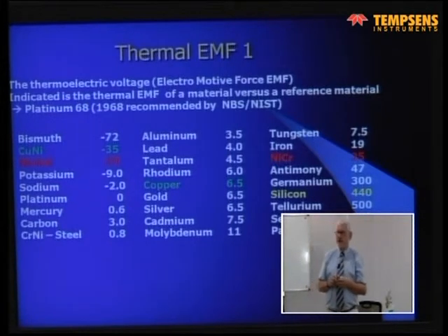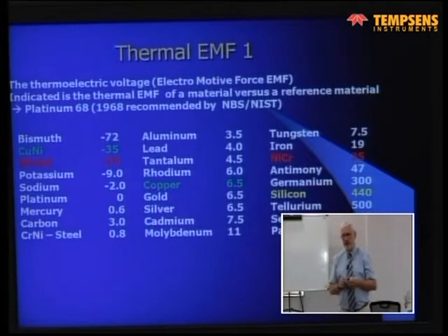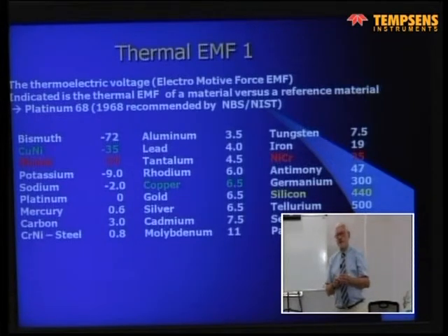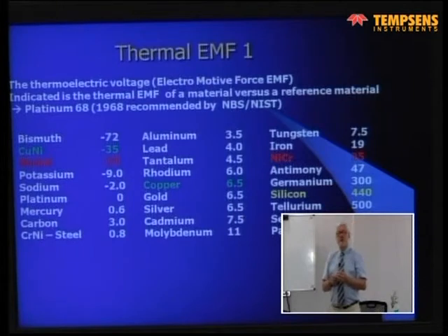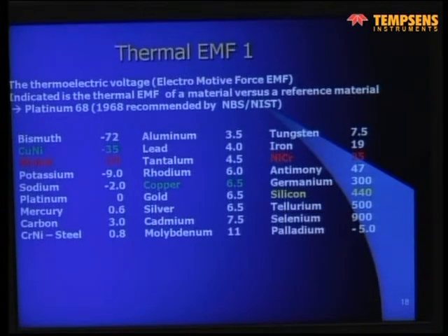When you look into the table in the 60584 international standard from IEC, you will find that the average coefficient for a type T thermocouple is approximately 41.5 microvolts per Kelvin. It is not constant. The temperature relationship and EMF for thermocouples is highly nonlinear, also in small temperature ranges.